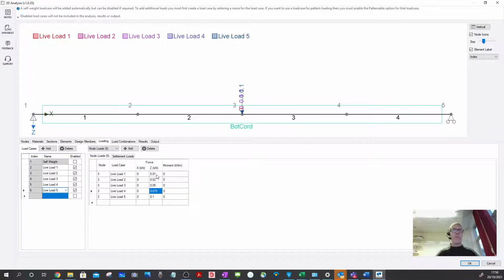If I take that off, and for load number 2, put a 20 Newton load, measure the deflection, take the load off, and put a weight back on of 50 newtons, measure the deflection, take that off, then put a load on of 75 newtons, measure my deflection, take the load off, then put 100 newtons in the middle of that timber, then measure my deflection, then take it off. So this is what we're replicating, but just using the software.